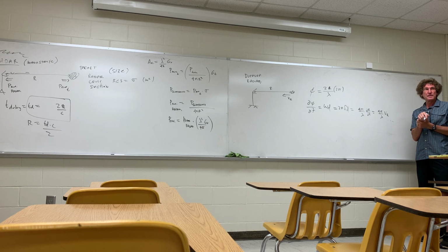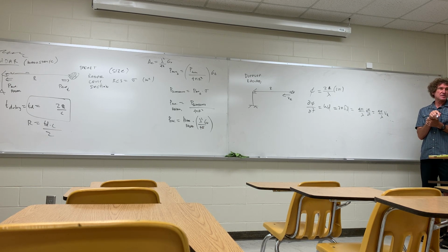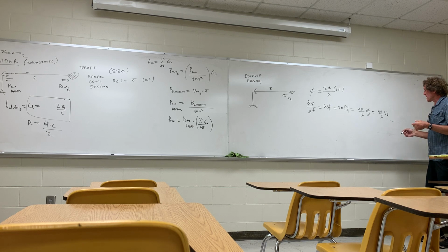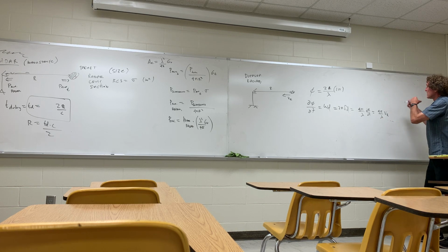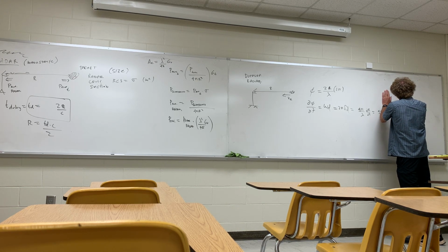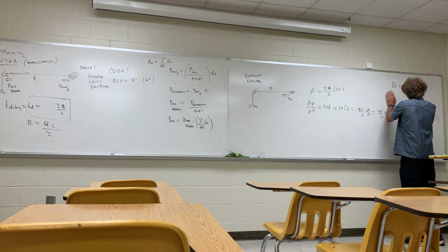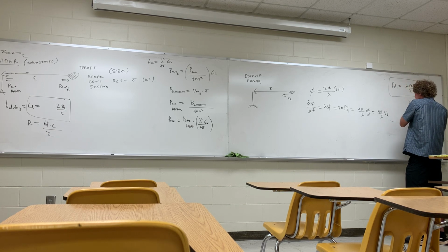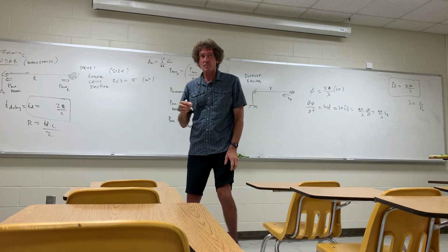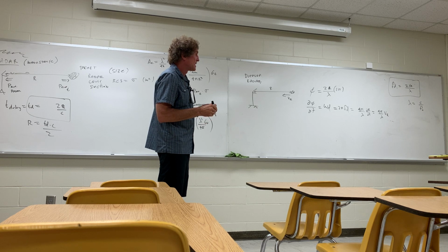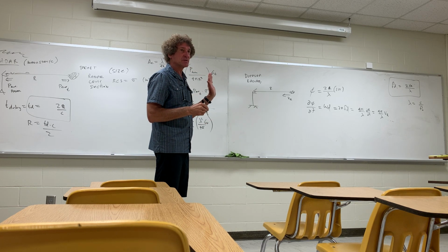You all follow me? I'm going to simplify this, but I want you to see the logic in it. Now, after that, I can say, well, if I'm only after Doppler frequency, I can take the 2 pi and divide it over here. Now I can find the Doppler frequency shift would be equal to simply 2 times V_R over lambda. And lambda is equal to simply c over f naught, and that's the transmitter frequency. I want to tell you this, that's the shift in frequency that occurs.